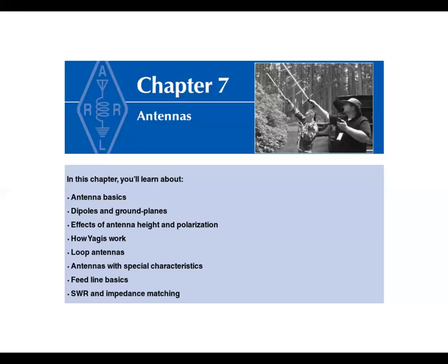SWR stands for standing wave ratio. And what that is, it's a measure of the energy transfer efficiency from the transceiver to the antenna. And we'll see what happens to the energy as it's being transmitted. Not all of it goes out the antenna. Some of it will come back to the transceiver, and that's what the SWR is used for, to help us understand that a little better.